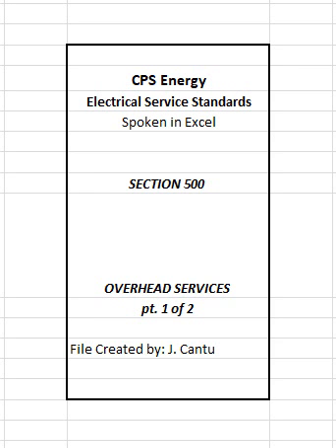506 Service raceway. The service raceway, S, containing the service entrance conductors shall be installed in a manner that will ensure proper clearances for the service drop conductors and drip loop in accordance with this section.